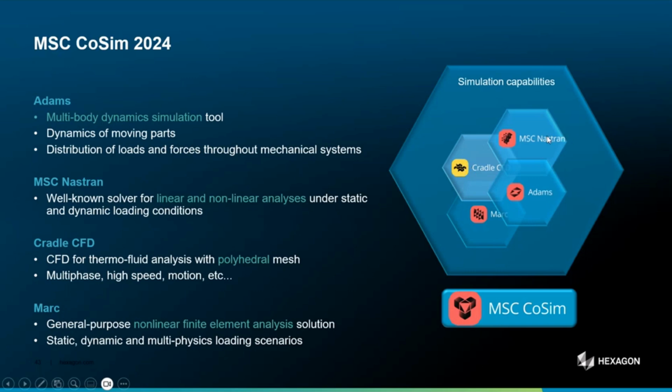So you need as well to come back to CFD. So you need to tell the CFD, the wing is not fully flat, maybe it's bent. And then the CFD will update its calculation. So maybe the force will be affected as well. So you have to make a coupled simulation, CFD and structural code working together. Otherwise, you won't be relevant in terms of accuracy.